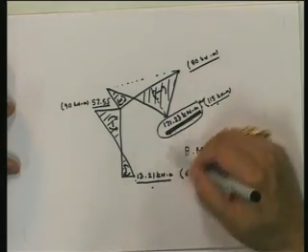There's a tremendous amount of bending moment variability, and bending moment variability essentially implies that curvature goes up, and you might have actually cracking problems, etc., if you have reinforced concrete. So by and large, increasing restraints in the structure is a good idea, of course, as long as you don't keep increasing it to a point at which displacement goes down and almost the entire forces are transmitted. If you take restraints beyond a certain point, you reduce the effect of the loads, but the member end moments go up significantly higher, and you no longer reap any benefits of making the structure stiffer.